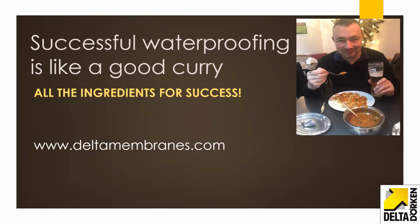Because DPMs like Visqueen, 1200 gauge polythene, aren't designed to stop water coming in. Is there a possibility that water could come in? Yes. Why? Because we can't predict what the site conditions will be like, or when the heavy rainstorm is going to put temporary pressure on it. So yes, put a waterproofing product, a type A membrane, under your slab if there's a step in it.